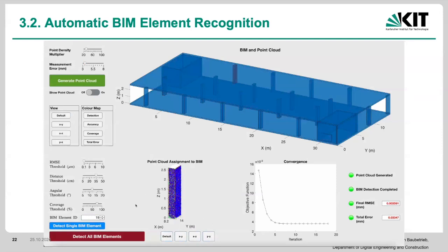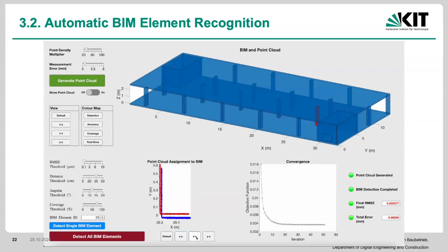So in this case, for instance, I think this is 3 centimeters. I apologize, I think this is not in millimeters. This is in meters. But what it is that it could give you is the total error from what the final version is to what it used to be in the beginning. How much did it need to move? And then this here gives us how well we've actually fit our model, which, as long as it's within the precision and the random measurement error of our instrument, we're good.